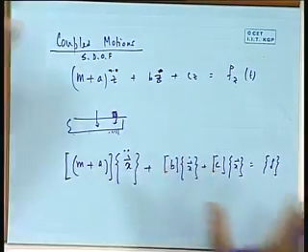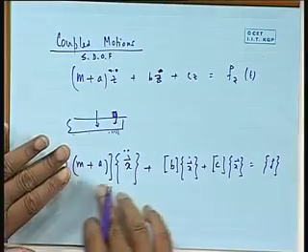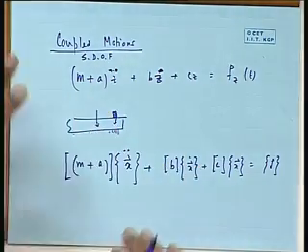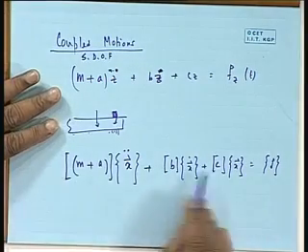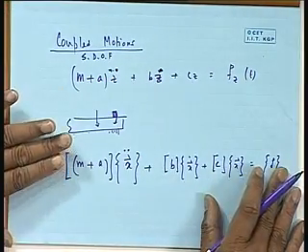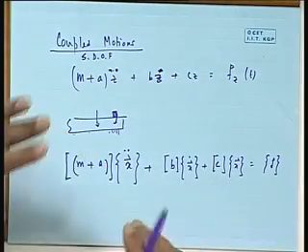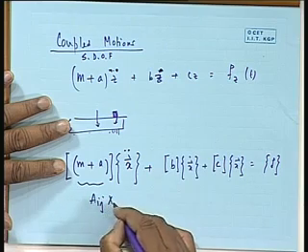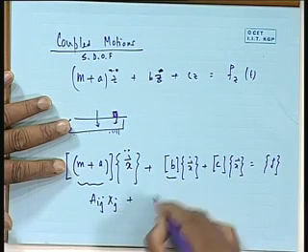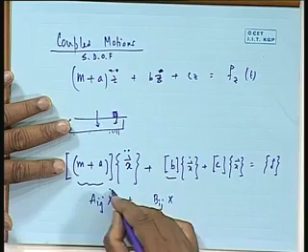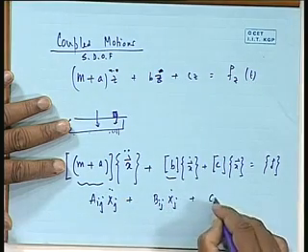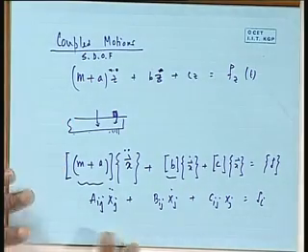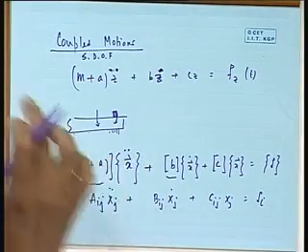What happens is that it becomes more complicated. I will just explain that to you in terms of the so-called coupled heave and pitch. What is the coupling between heave and pitch? Actually, we can expand that more. I will write that in a minute. So it becomes something like this. In fact, one can write, if I call this A, it as Aij into xj double dot plus Bij into xj dot plus Cij into xj equal to Fi. Like that one can write, because you see this will be a 6 by 6 matrix.